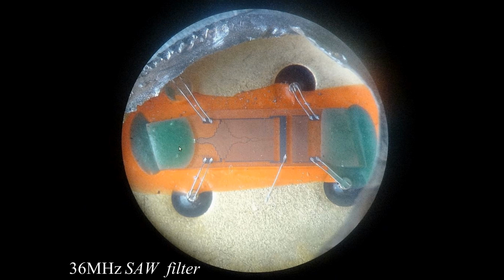There are other ways to remove these unwanted waves, but with cheap filters for cheap television receivers, with more complex electrodes we could remove the acoustic waves otherwise, say building a 4-phase feeding electrode, so to have the acoustic wave just in one direction. But for cheap filters with just one pair of electrodes on each side, we use resin here, and the insertion loss of this filter is very high.